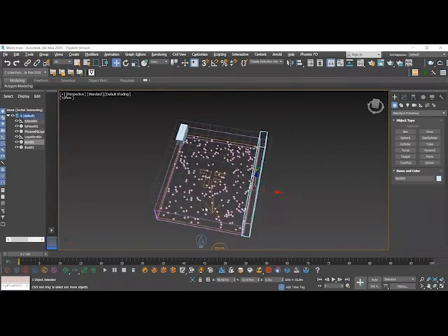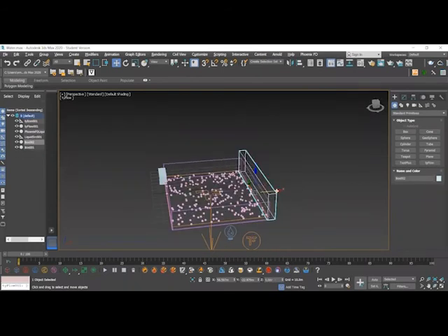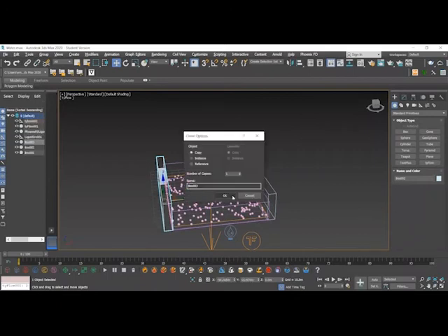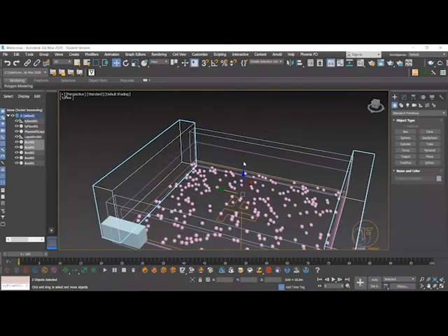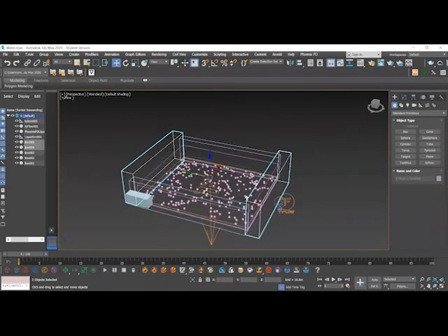So now this will not get rendered. Hold shift and drag the wall to the other end, and then repeat this for another 2 steps. Click OK as copy. So now we have boxes enclosing the whole area of where the water will be.